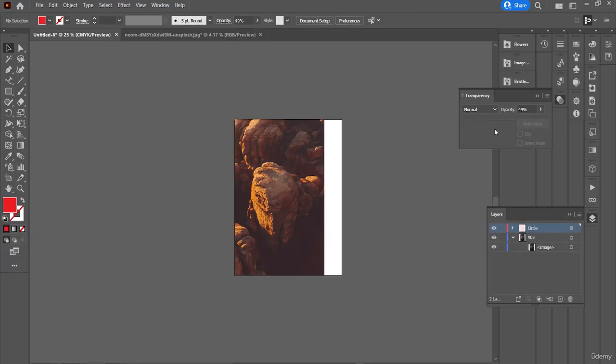Okay, so you'll be able to do a lot of things with layers and stuff. In layers, another advantage is that you can make another sub layer. You can click on this and another sub layer will be applied to the same layer. You can also group specific layers. Let's say I'm going to group all these together. So I'm going to press Control, Shift, and then down. Select them, whichever one you want.